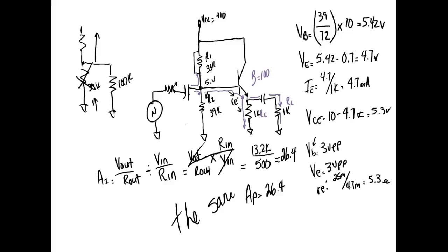By the way, very seldom see a resistor short, but we do see them shorted when people make mistakes. A lot of times when people are soldering, they drop solder on their circuit card, or they clip the leads too long, and then when they press them down, they bend out and short against other things. Normally resistors will open or the resistance value goes up.